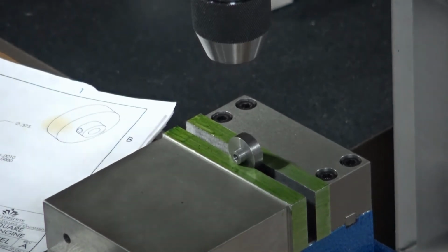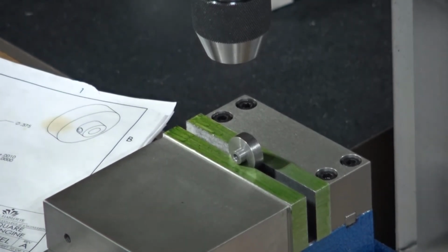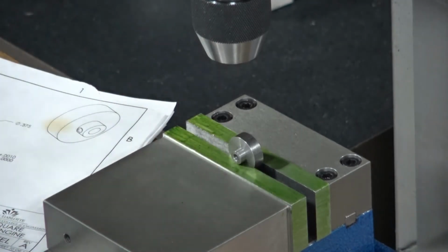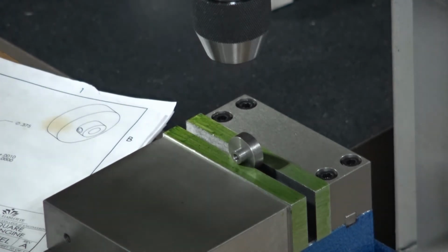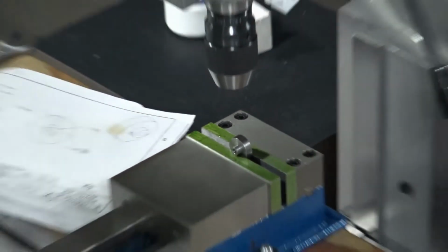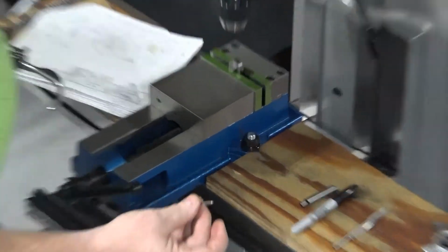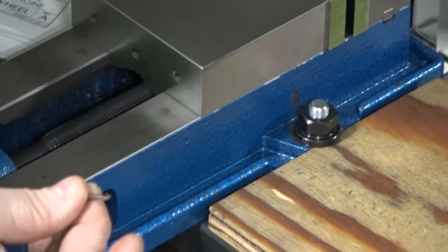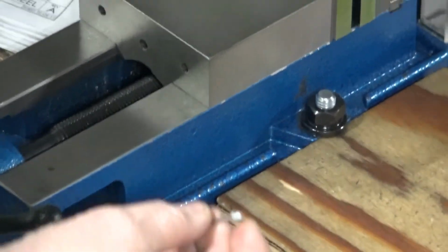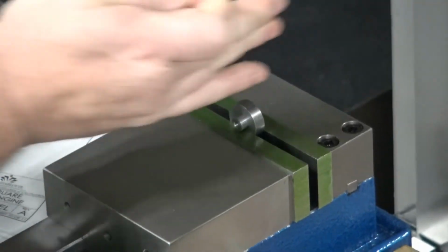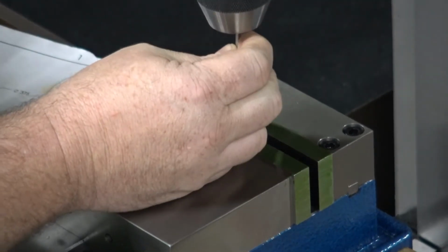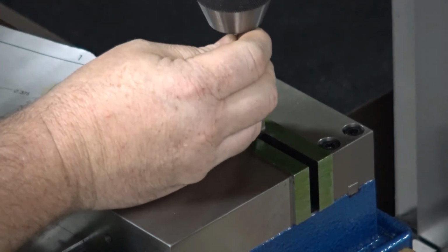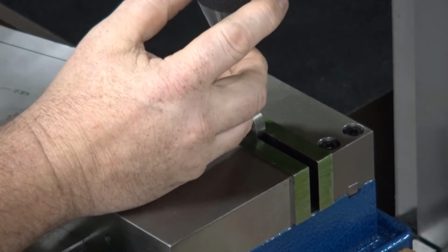Remember, our number 2 center drill is too large because of the clearance that we have up against this face of the flywheel. So we have a number 1 center drill, which the major diameter of a number 1 center drill is 1/8 of an inch. If you recall from our whiteboard conversation, we are allowed up to 150, so 125 is plenty small enough. So we're going to go ahead and reduce our chuck size down, and I'm going to hold on to my center drill.